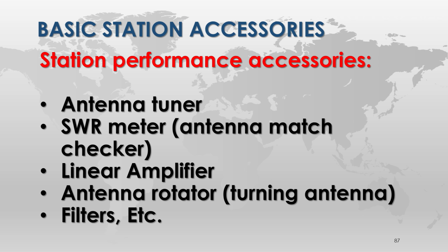Or up on the mountain. Yeah, there's a guy in Washington that can't hit the repeater in Portland. So he aims his antenna, he's in Washington State, he aims his antenna north at a mountainside, bounces the signal off, it goes back to the south and hits the KGW tower in Portland. And he can get into the peak radio system that way. But if he aims his antenna at Portland, it won't work because of the terrain.